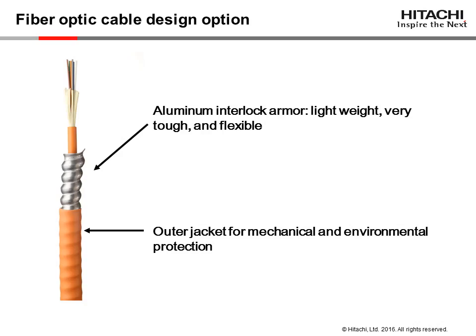A significant advantage of this cable design over non-armored ones is the elimination of a protective inner duct. Inner duct is a flexible tube pathway typically installed prior to a cable installation. Inner duct acts as a protective barrier, although it is plastic, and helps identify the cable. Installing armored fiber optic cables negates the need for the inner duct, saving time and money. It is typically available in plenum and riser-rated versions. A plenum-rated indoor-outdoor version is even available from a leading manufacturer.